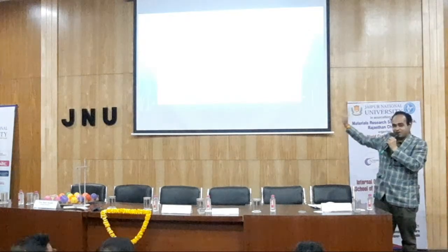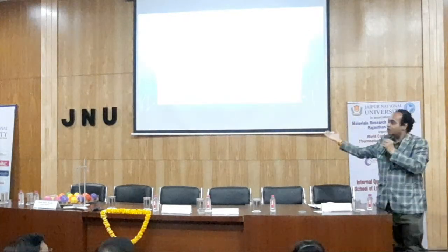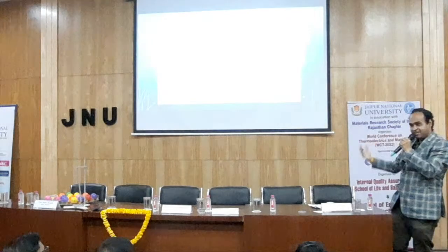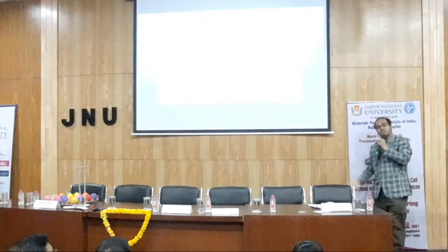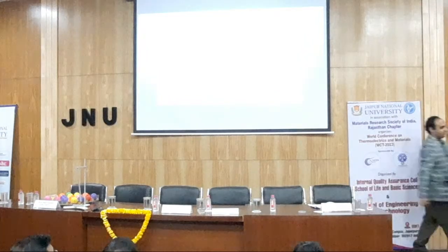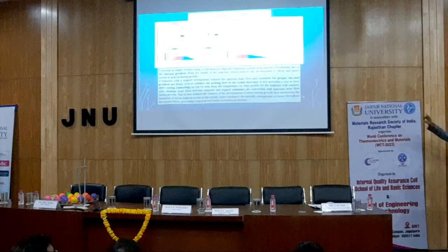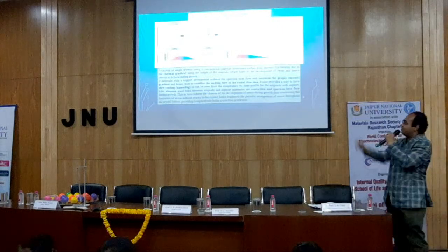But here the chances of multi-nucleation are maximum. If you go with the normal procedure, most chances are there for multi-nucleation, and the crystal quality may degrade and we may not get that quality of crystals. So we have done a modification in this. We have provided an ampule with a support arrangement. You can see there is a support we have given.